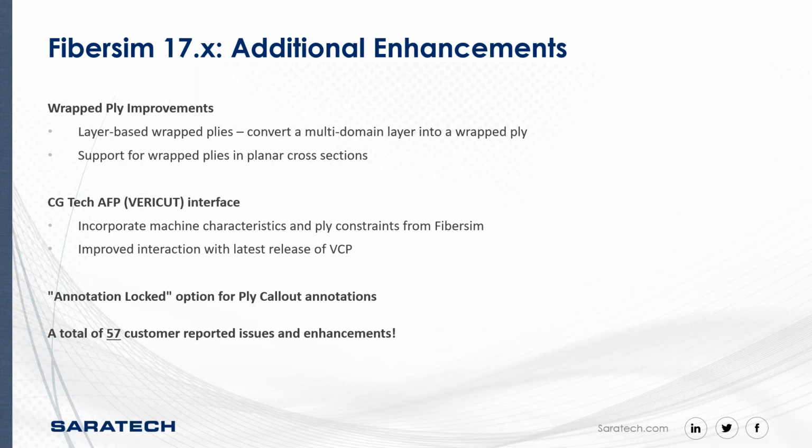Another one I called out here is what I call annotation lock. You may know that Fibersim can generate ply callouts or 3D PMI that might be a ply label, it might be a ply table, it might be something that you want to show on a view in 3D that you could then show to any other user outside of Fibersim. Fibersim can populate that ply callout with data about the ply, the thickness or the material, etc. And we now have the ability for the user to lock those annotations. So if you want to release the model and ensure that those annotations won't update, you can actually lock them, and Fibersim will honor that lock until you unlock those annotations, and then Fibersim can update those annotations as you see fit if you've changed the underlying ply information that supports those annotations.